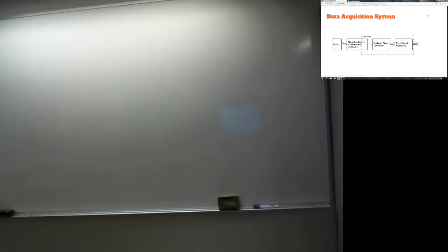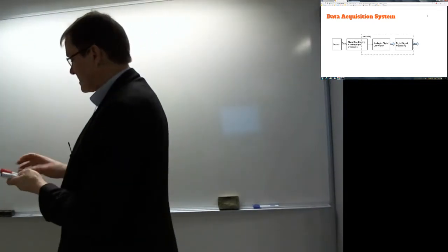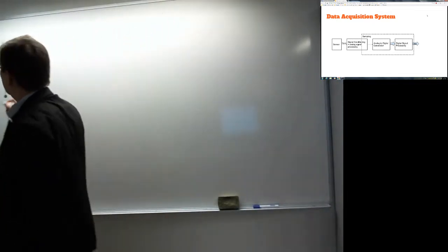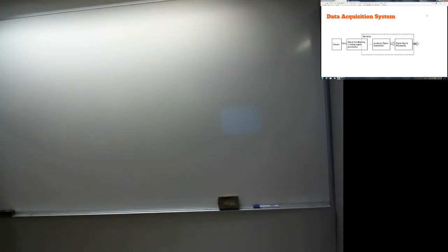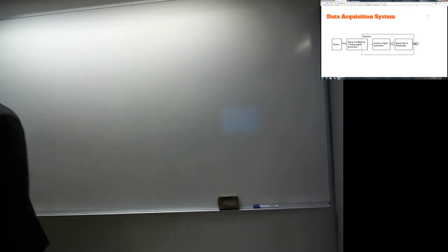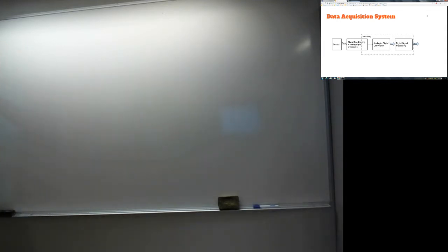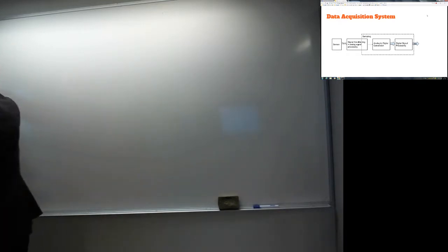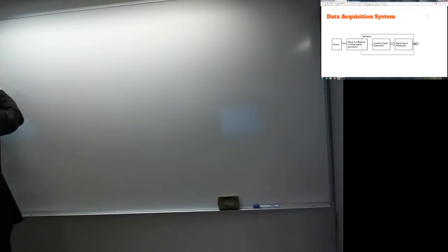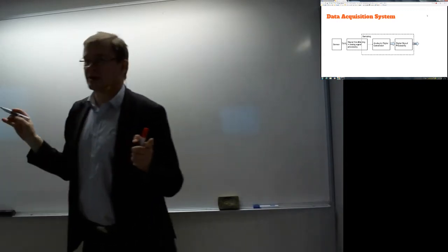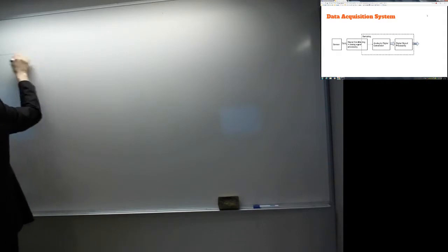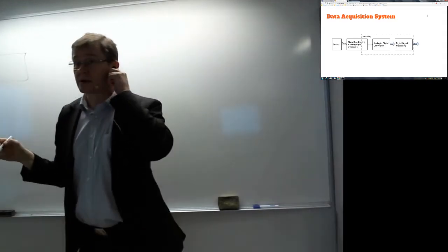Data acquisition, what is this all about? What we are talking about is a system where we have this sensor that just gives a primary signal, that actually has the transfer function to transfer the physical property into signal. So this is just an electrical signal. Okay, after that you need to do something for it. That's basically analog processing, which is signal conditioning.